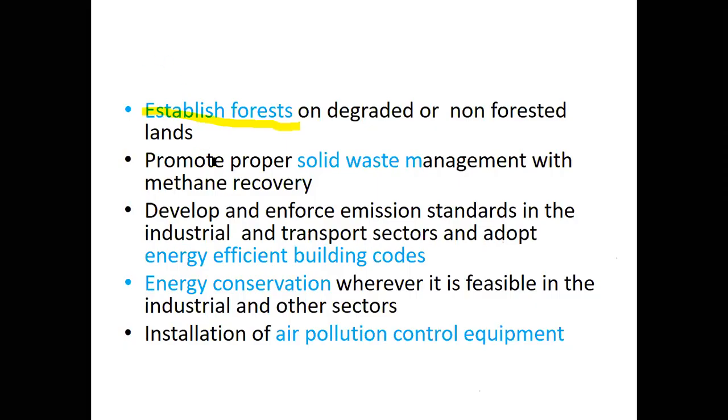Then promote proper solid waste management with methane recovery. When you refer to the solid waste management lecture, you may learn that methane is emitted from our landfill sites. We cannot avoid the emission of methane, but we can collect it, and then we have to burn it at the site.